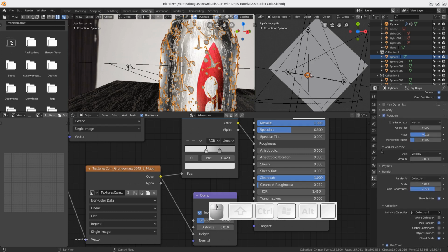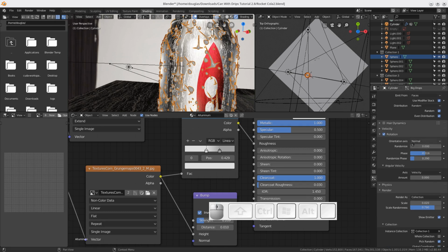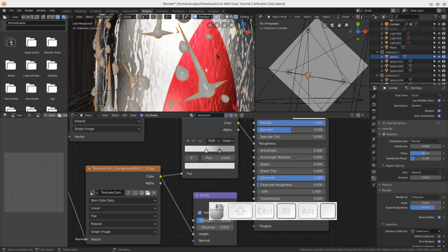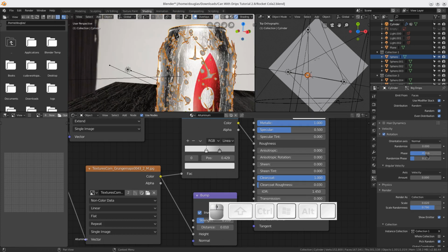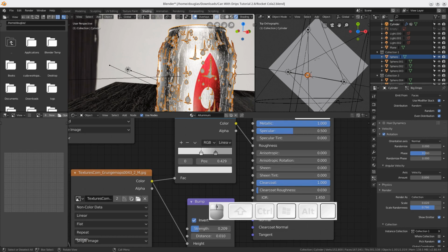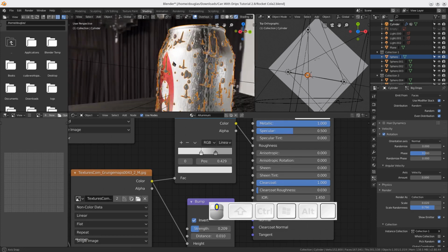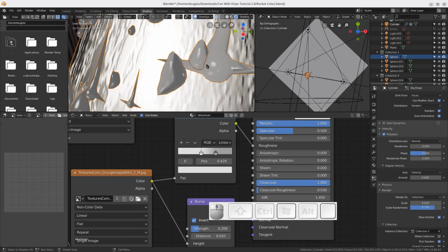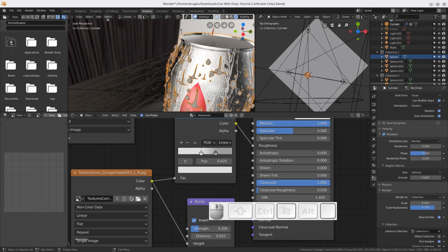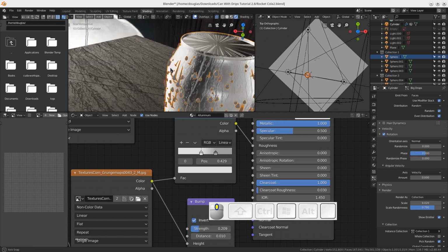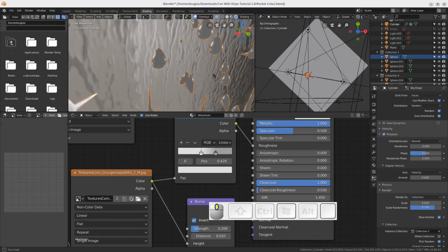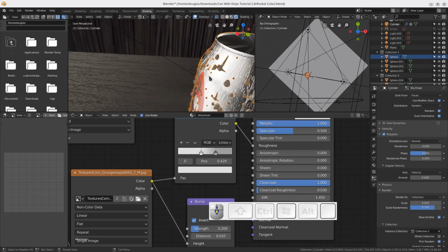So the next thing is rotation. We're only rotating about the normal. And actually I found that I really don't like much rotation on it. So to start with, if we put the phase to 0 and we put the random phase to 0, all the particles are shooting straight up. And that's why I put these axes on here. The other thing that's important to realize is that if we go into the can, you can see on the inside of the can, you're getting the other side of the particle. So you're only seeing half of what you design.